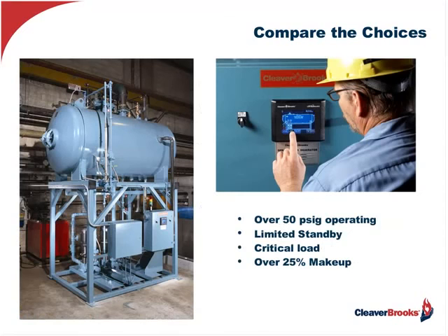If you're over 50 pounds operating, if you've got limited standby in your particular facility, it's a critical load, and you've got over 25% makeup, a deaerator becomes a very, very serious consideration. Very serious consideration. As does that high-pressure condensate return system that I spoke about earlier.